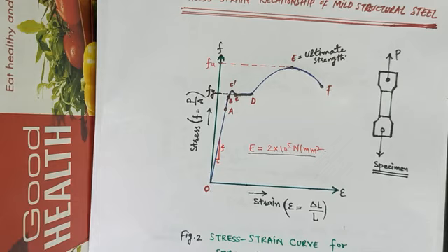This property allows the stresses in a steel structure to be redistributed. So it might also be said that a steel structure has a reserve of plastic strain that enables it to resist overloads and sudden shocks. If steel didn't have this ability, it might suddenly fracture like glass or any other brittle material.